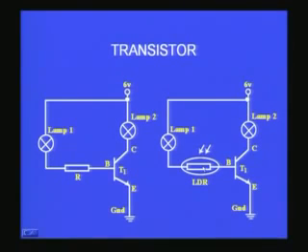The small and the high can be of the order of some kilo ohms and mega ohms. So the variation in this resistance can be brought about by light falling on it. Here I removed the 100 ohm and introduced 10k, 100k, etc. manually, whereas here that can be done by the amount of light falling on it.